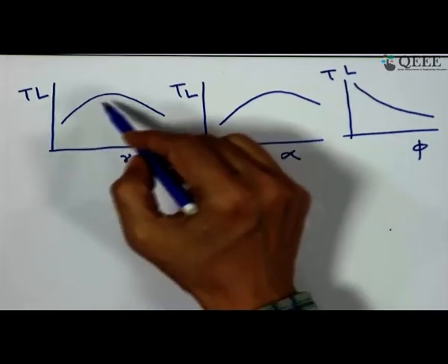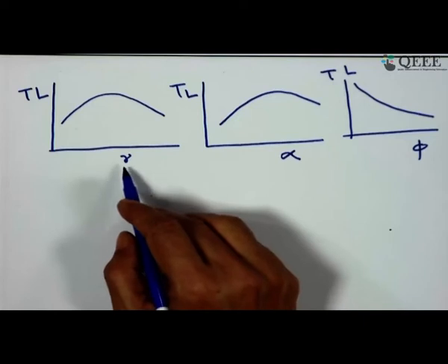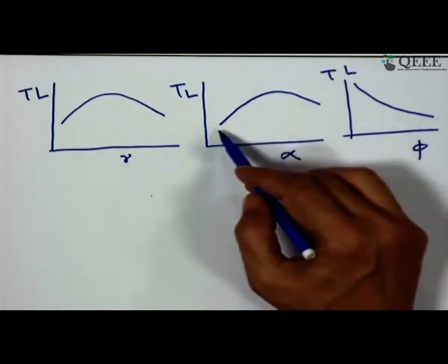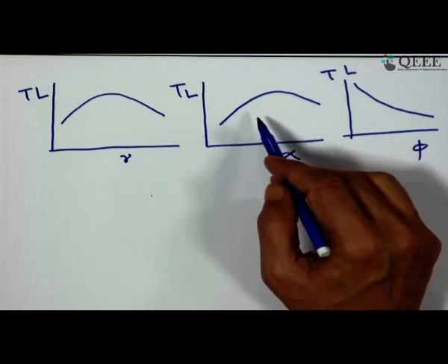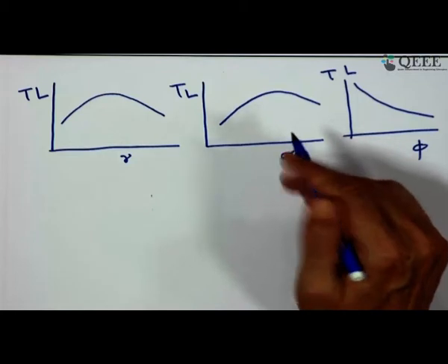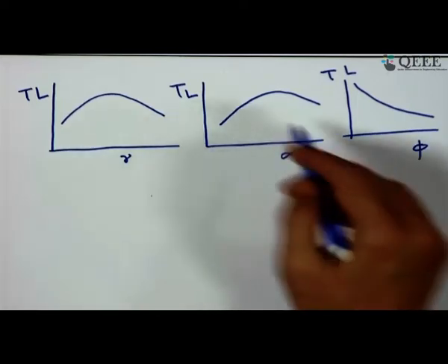But when we give further rake, then the mass of the tool available to bring down the temperature is less, and the same argument we can advance also for the clearance angle. In one case you have less rubbing, less temperature, and when you increase the clearance beyond a certain limit, because of the size of the tool and the mass involved on the tool being less, that may lead to higher temperature.